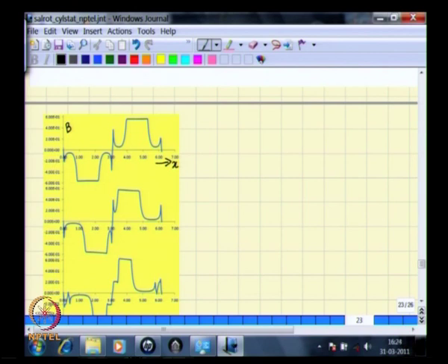Now you see this plot has been drawn for rotor angle at 0 degrees. So you see that the flux density is low in this area, becomes high here, goes low here, inverts in sign, becomes high here again. Why is this high here?